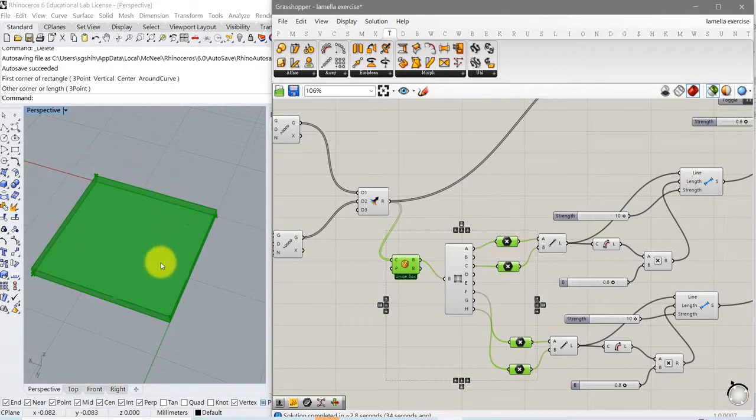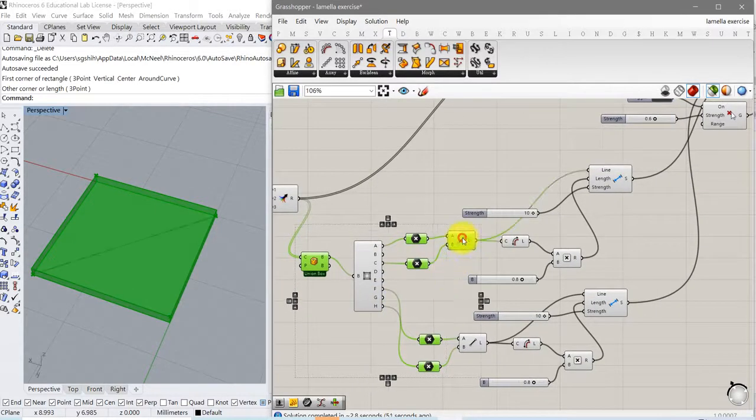So I use a bounding box, and there are 8 vertices for this bounding box. With this component, you get all the 8, and you just try to figure out the diagonal corners of them, and then you create 2 line segments across, and calculate the length, and then use the length to set the line length constraint.